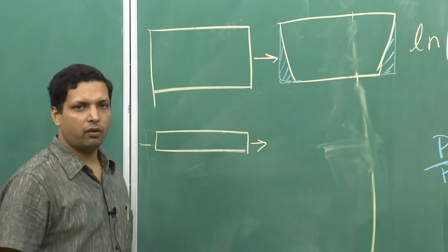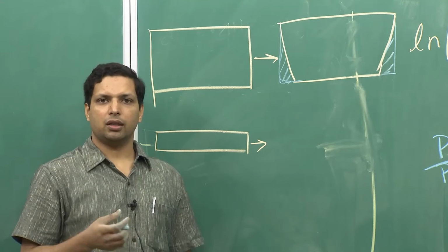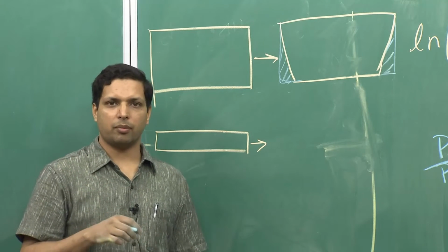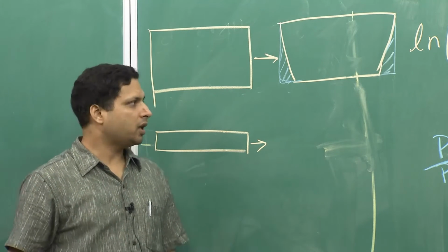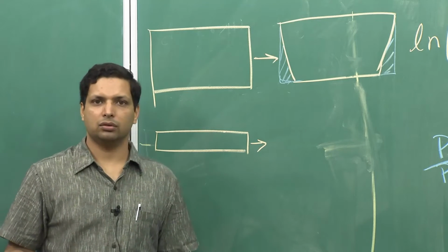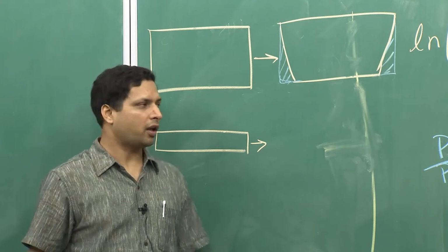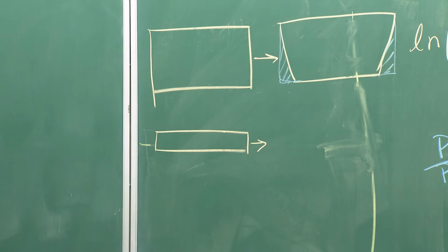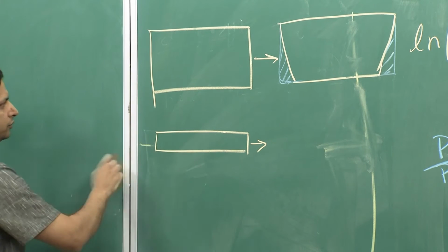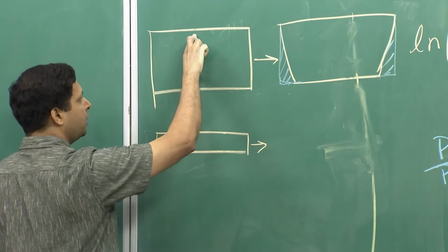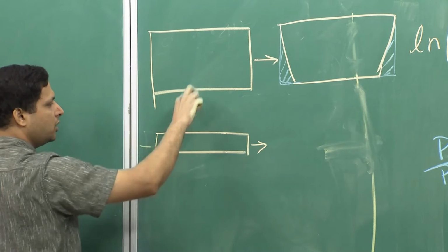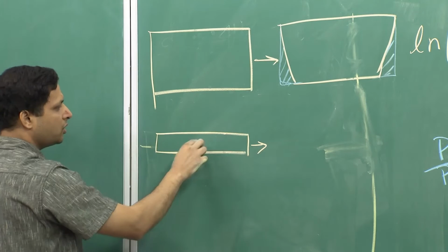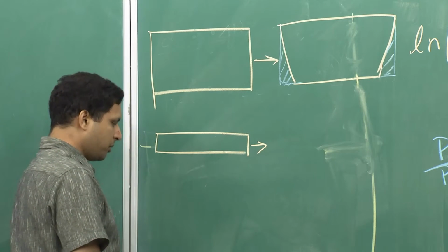We have seen that whenever you are applying a piston and pressure on it, there will be a pressure gradient, and the pressure gradient will lead to a density gradient and hence shrinkage. So, how to get rid of it? One way is what I have already shown here. If you have a component very long in the z direction, it will have a larger chance of shrinkage. Over here the shrinkage will be much smaller.